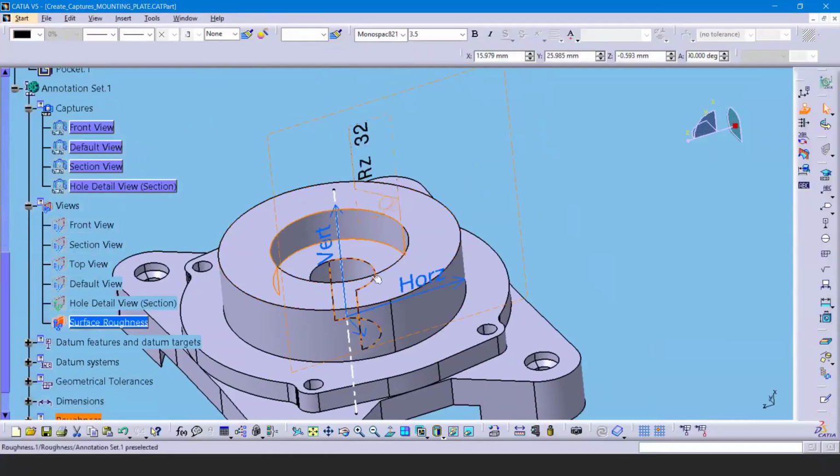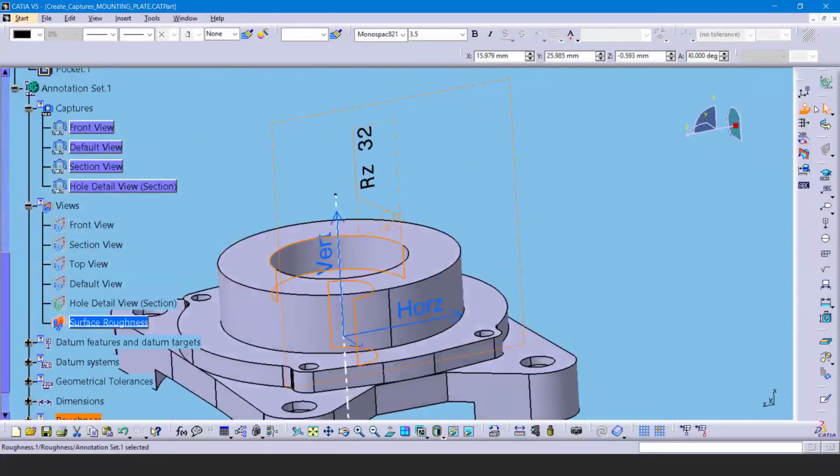And again, the reason why both of them are highlighting is because my 3D annotation query switch is set to be on. If I turn this off, it's not going to highlight anything. So again, it's one of those buttons that people kind of turn off and on. But that's one method. But let's say that you want to make this even more evident, that these two surfaces should be the same surface roughness. What you're going to do is utilize some extracted surfaces.